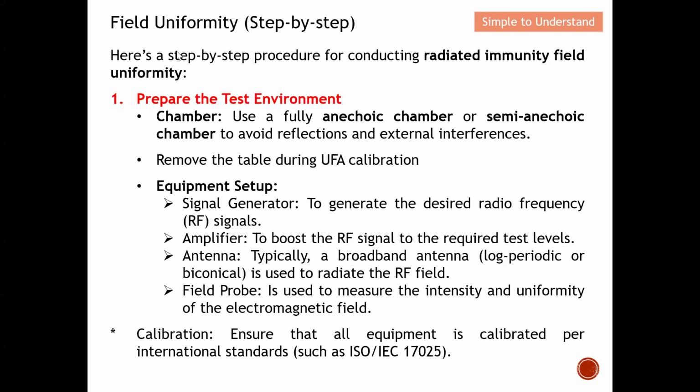Okay, let's go into the step-by-step procedure. Before we can do this radiated immunity test, we need to do this field uniformity. Let's understand step by step how we can perform this field uniformity.